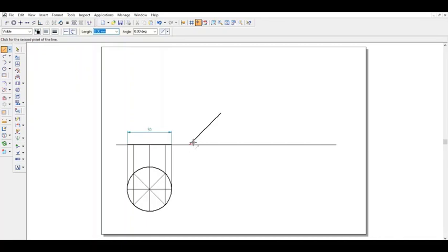Now the projection lines here are very complicated. So one step you have to follow is to name the points first. I am not naming here because it is consuming time. So what I'll do is, I know that these 2 points are endpoints. I'm just projecting these two. So I've got 2 points here. Next, I know that at the center I'm having these 2 points here.